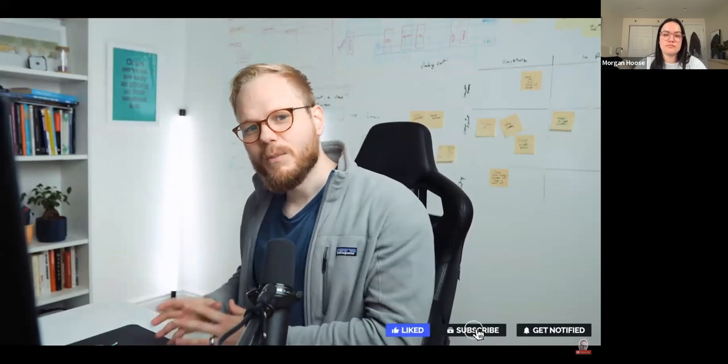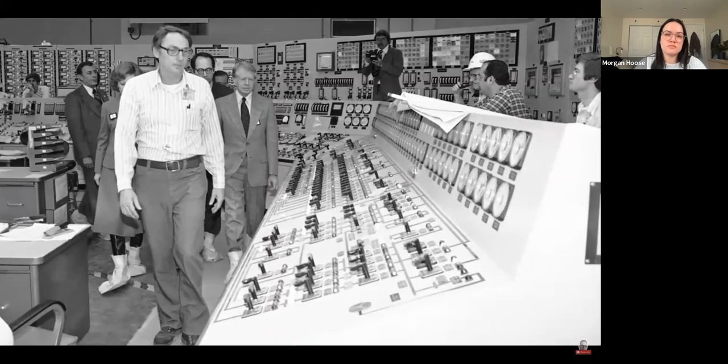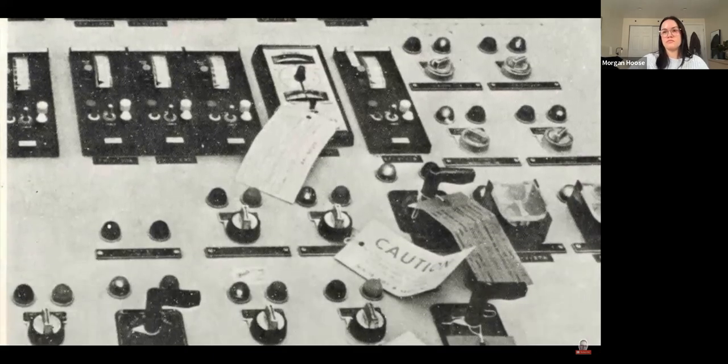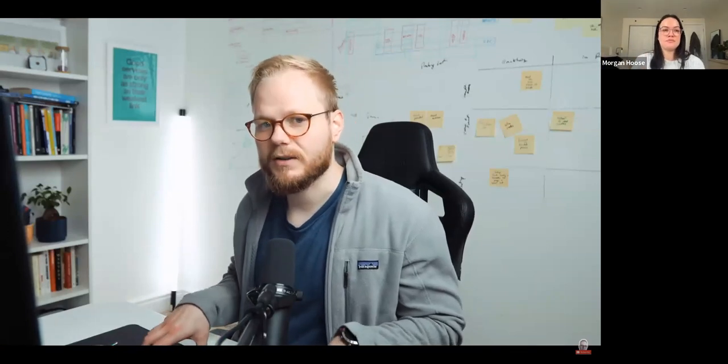This is a mouthful, right? But it's almost attributing it to poor UX, which didn't consider proper training or the human factors, the perception of the actual control instruments. On a very high level, the light which indicated whether a valve was on or off was partially open and the users couldn't tell. And that oversight led to a partial meltdown.